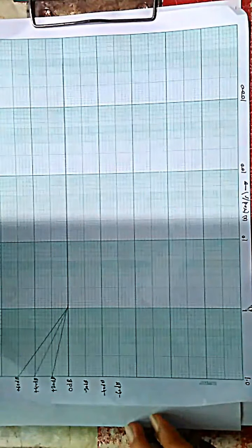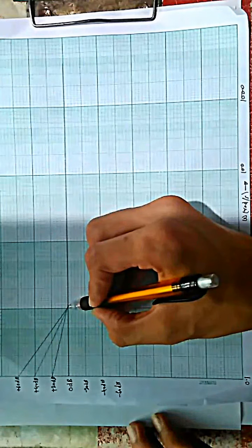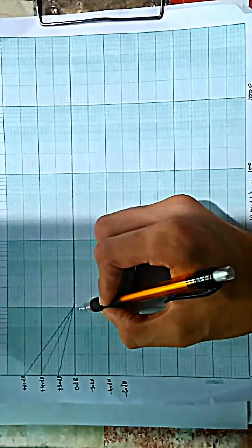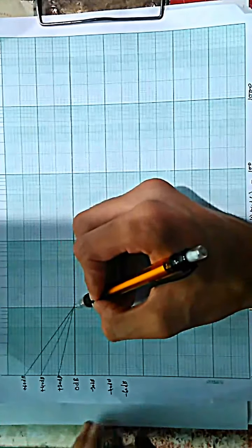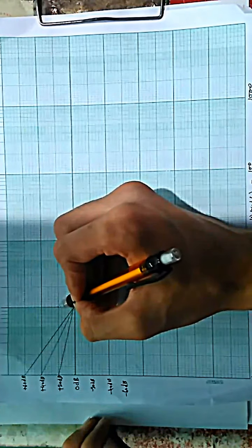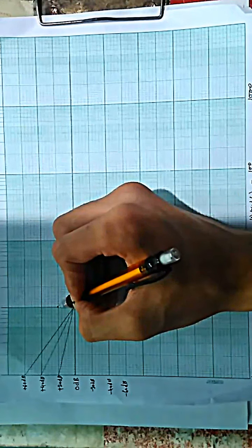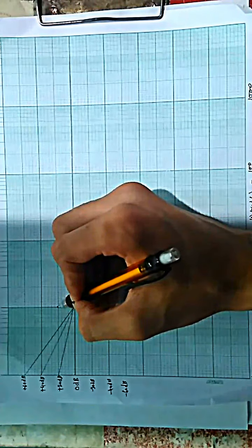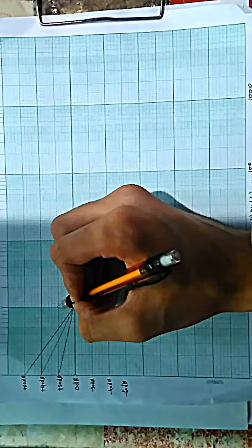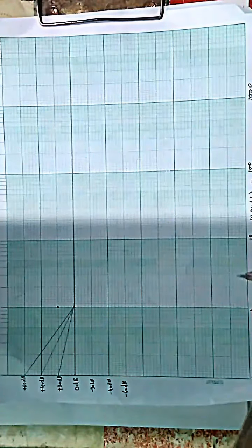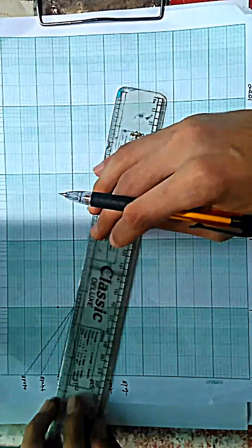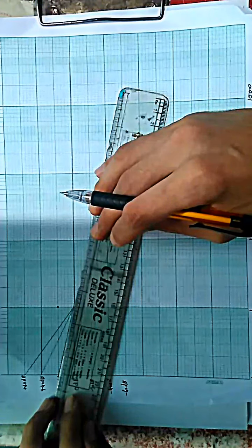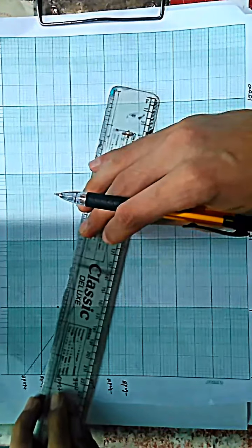Omega is equal to 1 is here, 0 dB here. Since our first column says 20 dB, just add 20 dB up. This point shifts to here. This is the work of gain. Now here we'll draw a line of minus 20 dB per decade, parallel to the minus 20 dB per decade reference line.